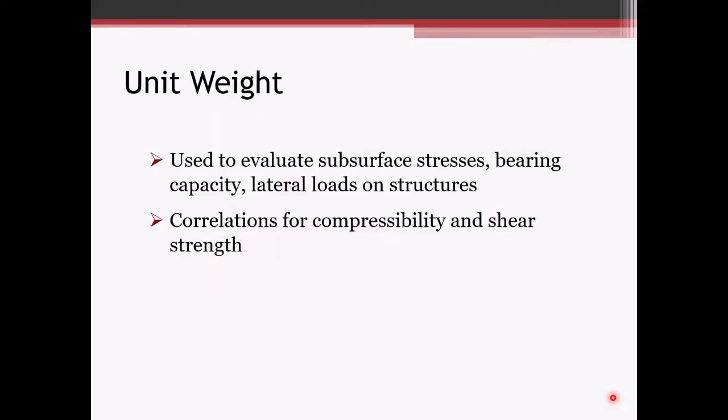So moving on to the unit weight. The unit weight of soil is important to evaluate subsurface stresses, bearing capacity, as well as lateral loads on structures. And it's applicable to soils that will retain their shape. They do have to have some sort of cohesion to them. It's basically measuring the weight per volume of the intact sample. And there are correlations for compressibility and shear strength based on the unit weight.